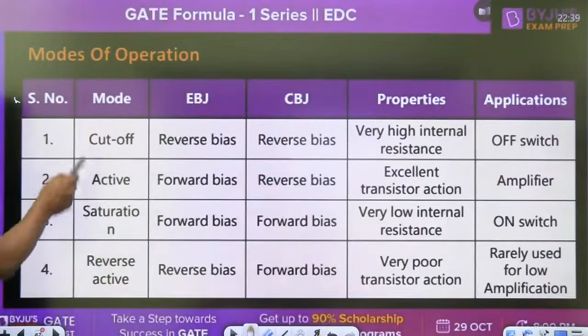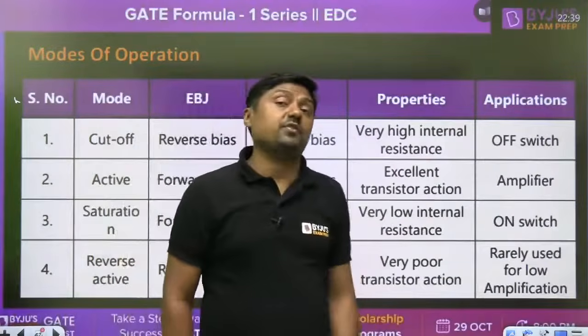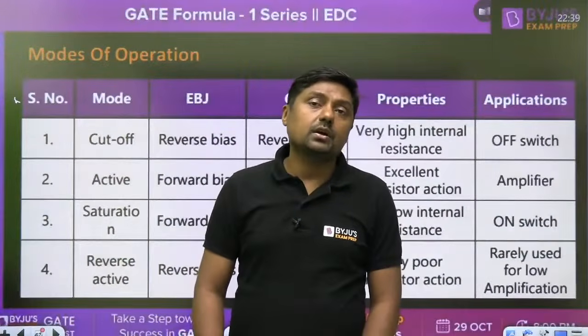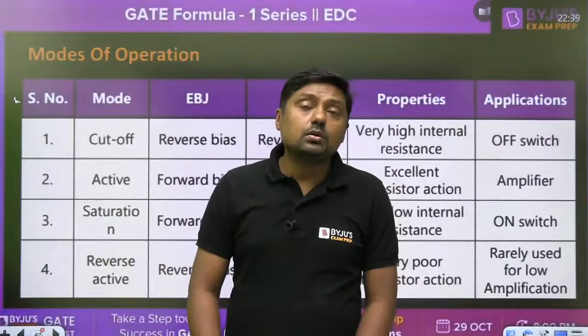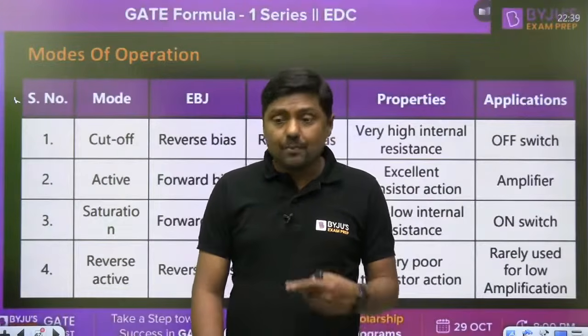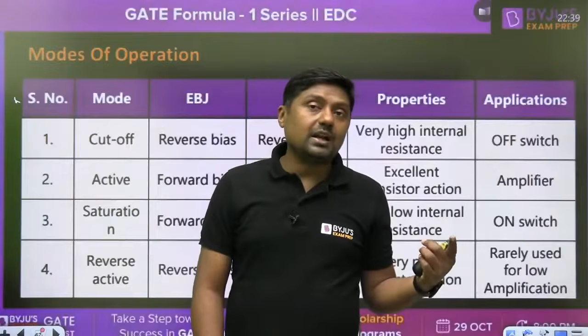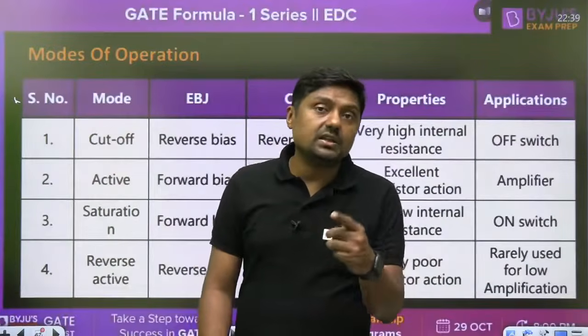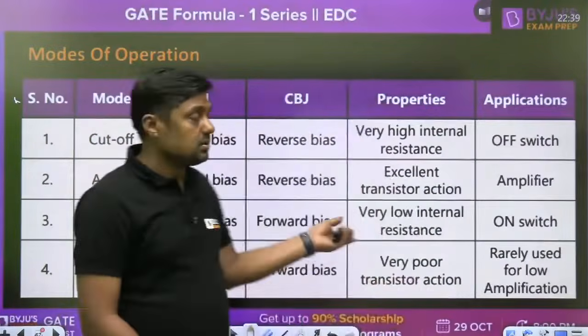In cutoff and saturation, it acts as a switch. Normal active mode we use for amplification, while reverse active mode is rarely used, only for low amplification. No doubt we use it, but for low amplification. For example, we use reverse active mode in TTL, transistor transistor logic. Yes, that is the use.